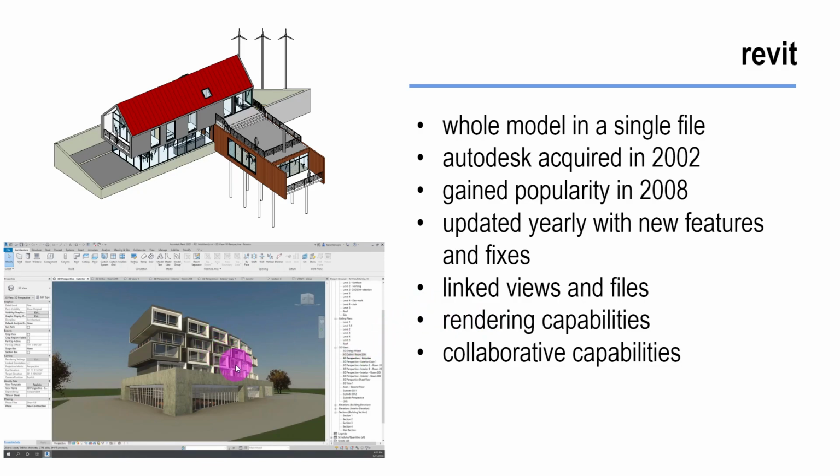So Revit does have its own render platform within the software. However, it's not all too amazing. We actually have a plugin that's installed on all of the desktops that does it a little bit better. But what these renders do is they create our perspective style views. We can do a 1-point or a 2-point.